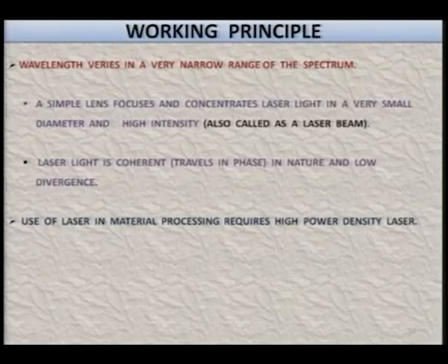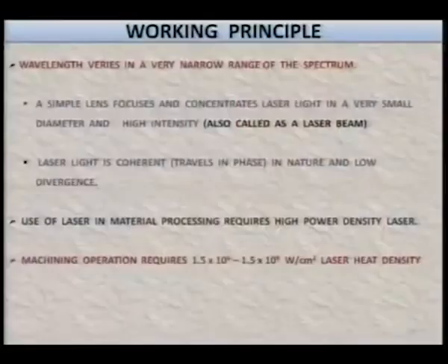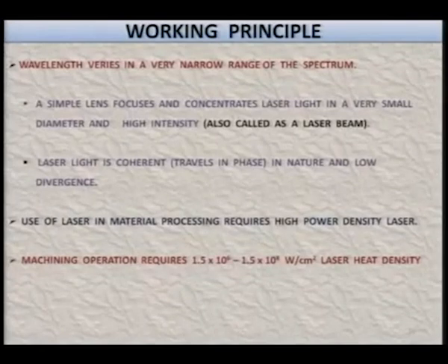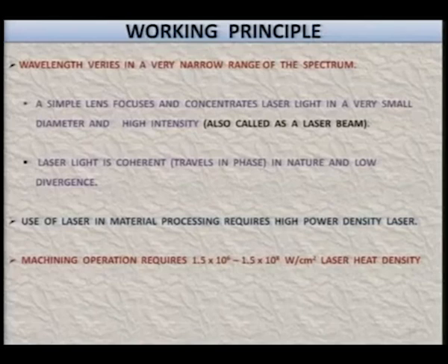Use of laser in material processing requires high power density laser. Now, there are certain applications, as we will see later on, for example the metrology applications, where you do not need very high power density lasers, a small power density laser can do. But there are certain applications, as we will see, like cutting, where you need high power density lasers. Machining operation requires 1.5 into 10 raised to power 6 to 1.5 into 10 raised to power 8 watts per centimeter square laser heat intensity, which is very high.